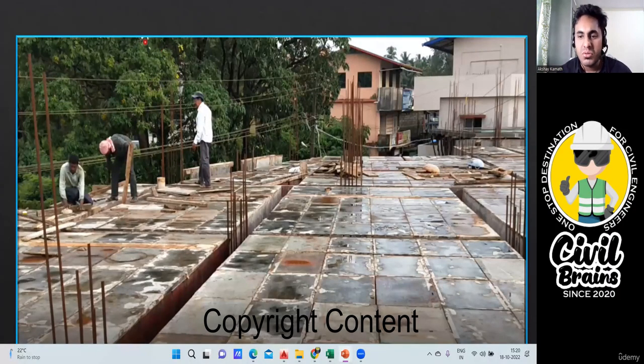Already you know that. So this is one slab panel what I have. I'll start from here. I'll take this length from this beam outer to this beam outer. Again, this beam outer to this beam outer. Both are same breadth. And from this beam outer to this beam outer, I'll get this length. I'll get this breadth. If I multiply, I'll get the slab centering area. You're getting my point? Very simple.